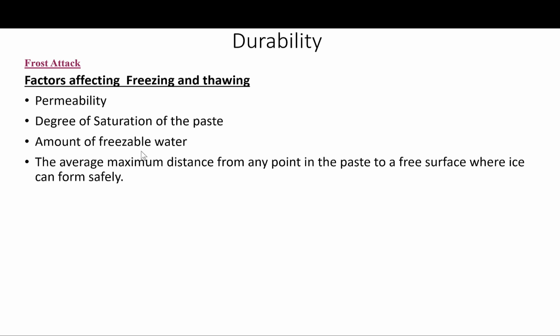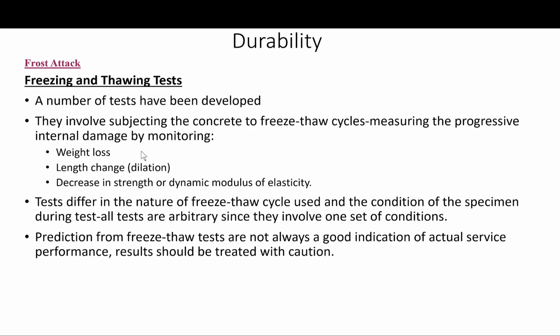So we looked at what happens during freezing and the possible explanations for the damage, and how the provision of intentionally added air bubbles or air voids will serve as safety valves to relieve the pressure that will develop once the temperature drops to a certain level where the water in the pores starts to freeze. And we have now looked at the factors that influence the freeze-thaw damage, and of course we want to control and mitigate them in order to prevent damage. So let's look at what are the available tests to assess the potential for freeze-thaw damage.